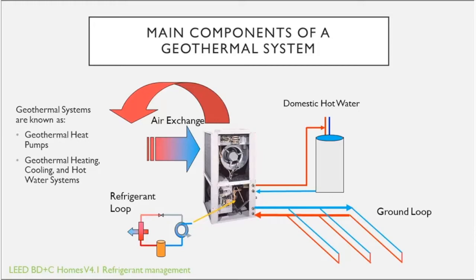Yeah, forgive me, sorry. It's not typically a conversation that we have a lot of, but we use all R410A now. No one uses R22 anymore, and that was the refrigerant of the past. It was actually a very efficient refrigerant, however, not environmentally friendly. So now we try to stick to the path of what everyone in the industry is using as much as we can, which is for now our 410A, which is included in that list. And in the future, that's probably not going to be the case.